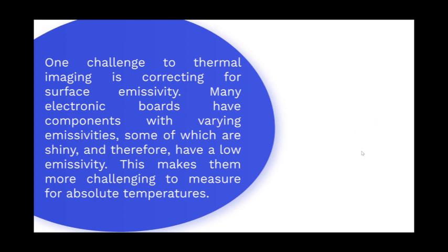One challenge to thermal imaging is correcting for surface emissivity. Many electronics boards have components with varying emissivities, some of which are shiny and therefore have a low emissivity. This makes them challenging to measure for absolute temperatures.